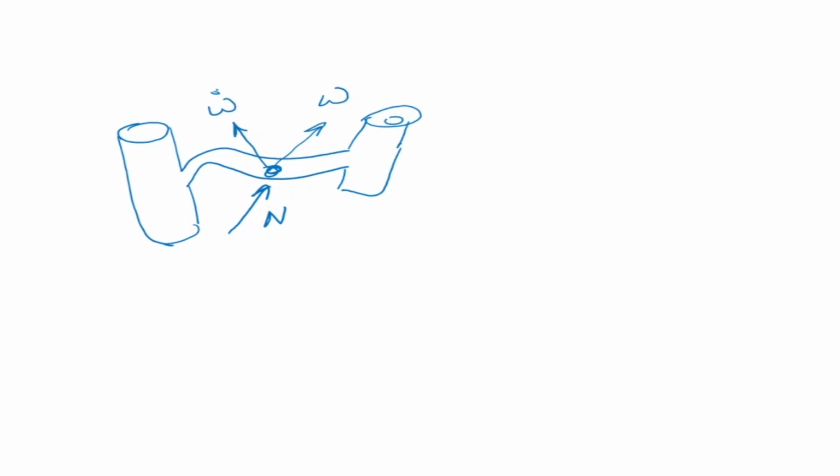Okay, so this is a rigid body subjected to a moment, and it has an angular velocity and angular acceleration. The equation that defines this moment is N = I ω̇ + ω × Iω, where again this is at the CG of the link. This is the inertia at the CG, with the origin of the inertia tensor located at the CG of the link. That is why we are writing I_C. So this is my Euler's equation.